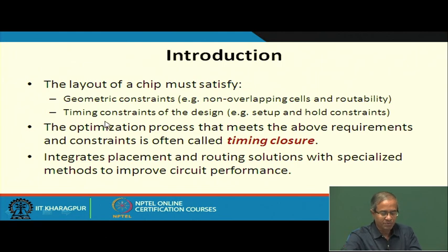and the second kind of constraint we have already talked about earlier, that when you have the storage cells in a system, the flip flops or the latches, these storage elements will have some inherent setup and hold requirements. So, you recall what was the setup time? Whenever a clock edge comes, how much before that I must make my input stable, that is the setup time, and the hold time says after the clock edge how much more time I should keep my data stable, otherwise the flip flop may behave incorrectly, right.